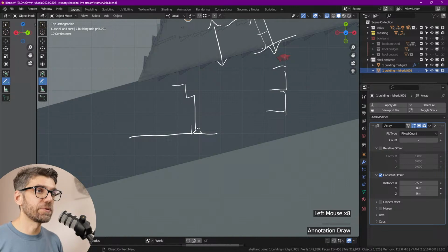There are possibilities of having a column that's running along the perimeter where it should be for most of the distance, and then transferring that column over. It gets more complicated, more difficult. We want to try to avoid this as much as possible. So the simplest thing to do, like we have here with the setback, is to reduce the size of the setback and just have columns here.